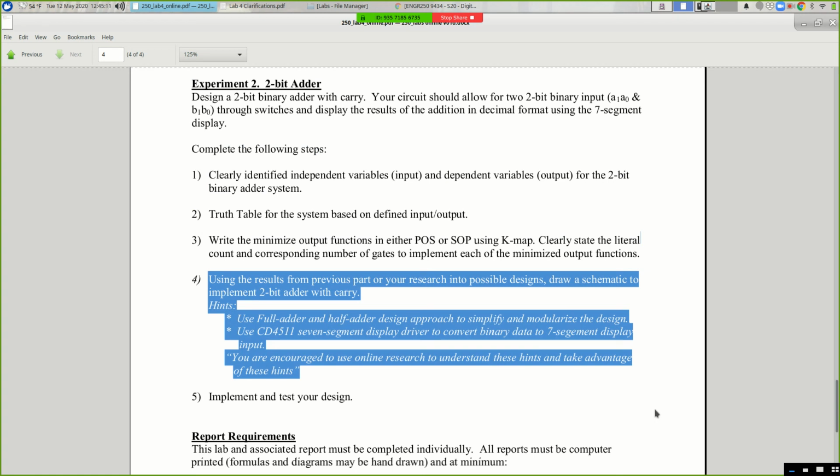Is there an instrument on Tinkercad that represents a full half adder? There may be, but if there is, you're not allowed to use it. We want you to do the whole circuit design and implement it yourself from primitive gates: ANDs, ORs, NANDs, NORs, XORs, XNORs, and NOTs. In practice, if you go to a chip supply, you can get chips that do half adding and full adding, usually multiple bits. But if you find it in Tinkercad, don't use it. Build it up by hand from these first principles.